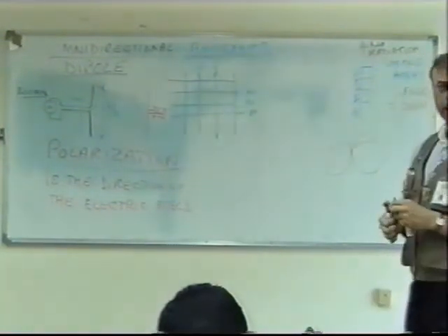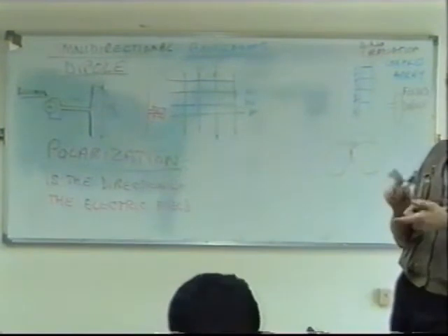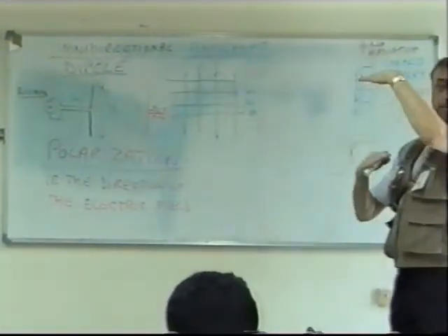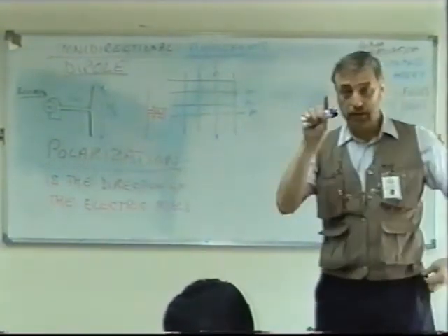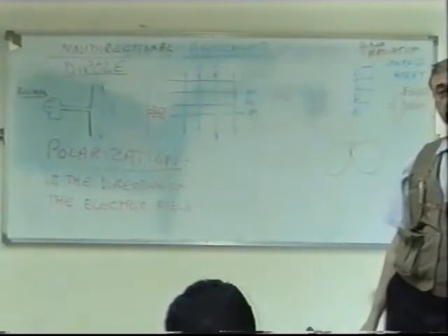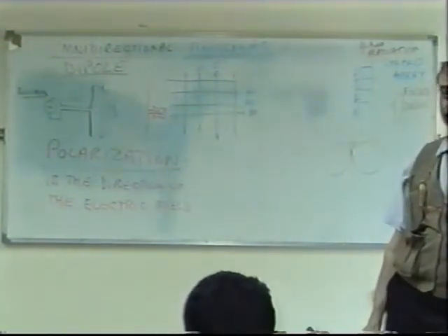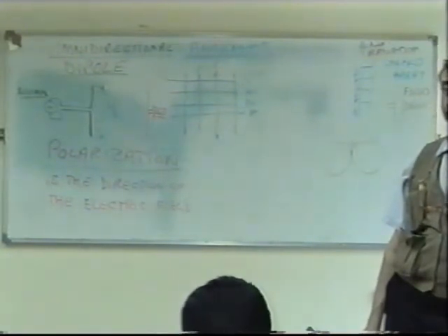They're all connected to the same transmitter, but the way it's connected is a complex phase difference. The distance between each dipole is also critical. It's got to be carefully measured. It's a dipole. Yeah, so it must be half a wavelength, each one.